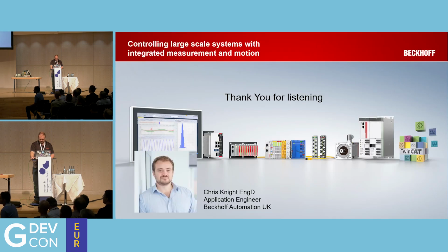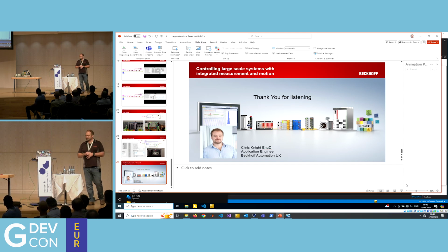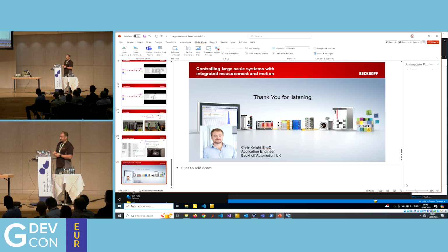And then a more technical one. Where are you doing the translation from Ethernet to Profinet? You mentioned a combination of Profinet and Ethernet in one of the examples you showed. So are those networks just talking to LabVIEW, which relays data between them? No, both those networks are talking to TwinCAT. TwinCAT gathers all the data together in one place and offers it up to LabVIEW. So TwinCAT is a centralization of all of those systems because it gives us the ability to use all of them without having to use multiple different vendor systems in our application.